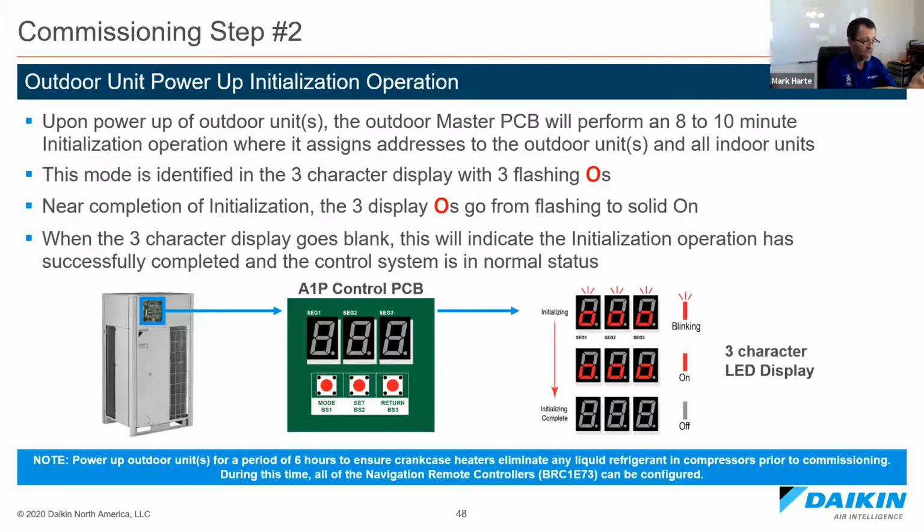Why is this key? For reclaiming, if you have to reclaim it. Say you're installing it and the electrician powered up the indoor units. Anytime you power up an indoor unit, the electronic expansion valve inside goes to fully closed. It shuts. It has to have a starting position. So say you go to pressure test and the electrician powered up all your indoor units. Where's your pressure test going to stop?